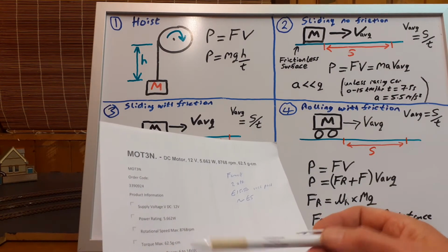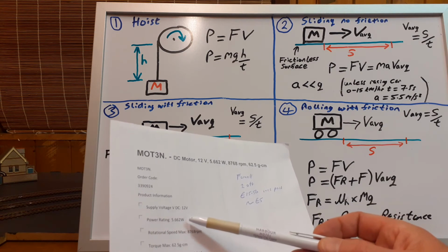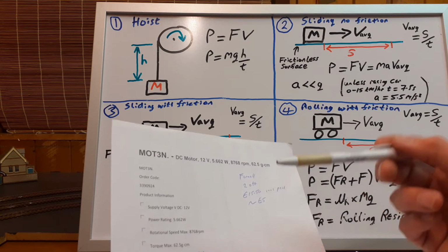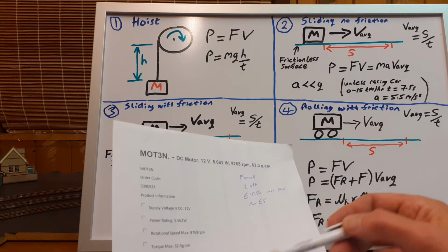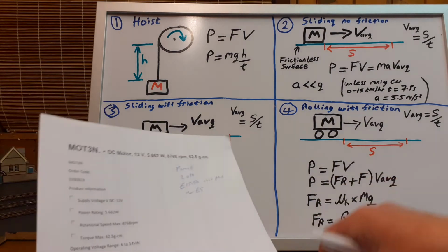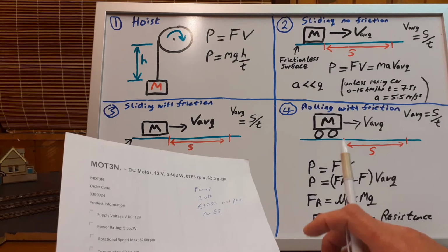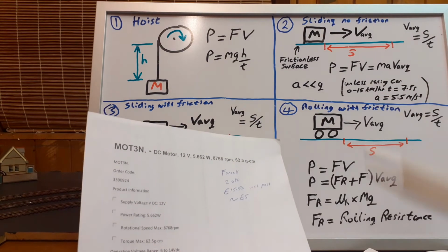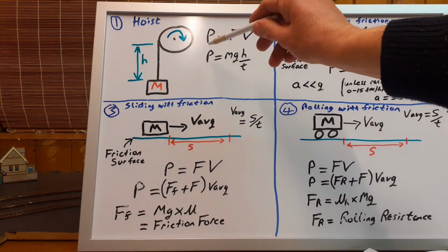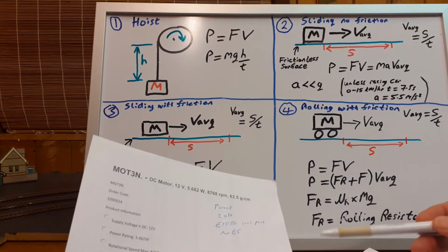However, when I did the similar hoist test on that, I got about a 10% efficiency. In other words, the mechanical power was about 10% of that, much less. And that is, I believe, common for small motors. I read this on some website where they're doing tests on these, that an efficiency of 10% of the rated wattage is thereabouts. And that's why my point that this is kind of 10 times more than you actually need. Therefore, it might give you the wattage you might actually use.